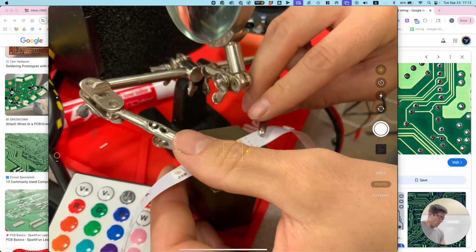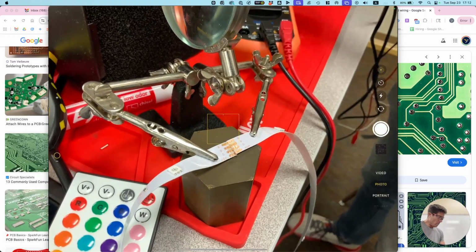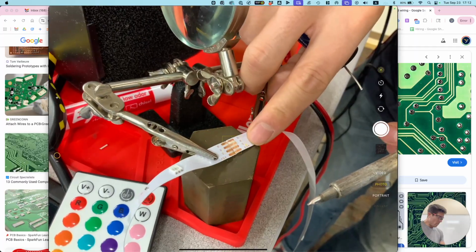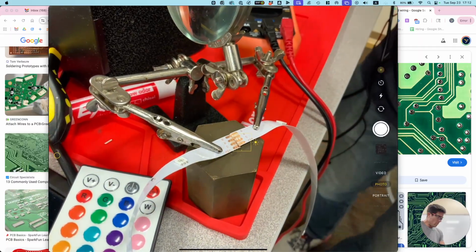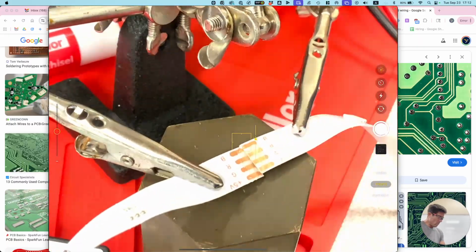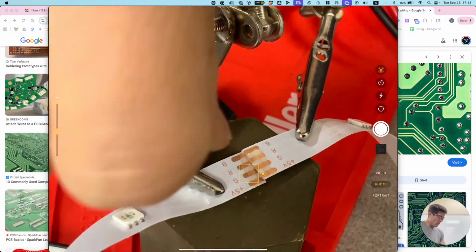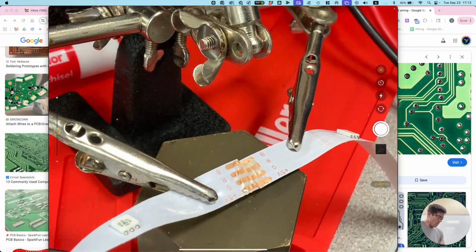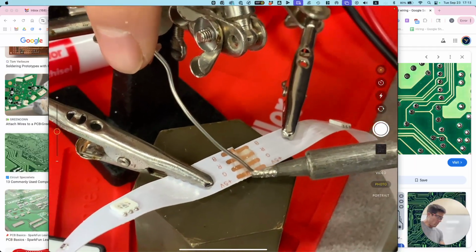Before I finish putting this back together, I was thinking. All right. Solder, flux, line this up. Once I get my first joint on, it won't be moving all over the place. Do you have to worry about the heat messing up the rivet? What's that? Will the heat mess up the rivet? If you dwell too long. Okay. So that's the general case with all of our soldering. Don't dwell too long. Just get in there. You notice when I'm soldering, I'm pretty quick.